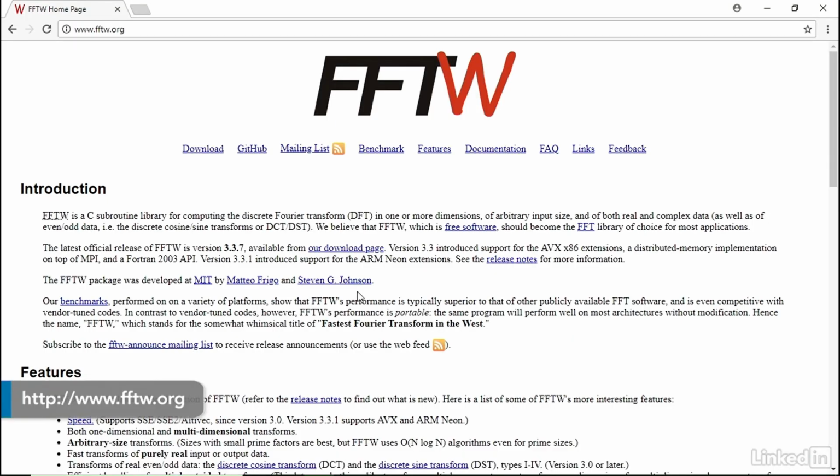Here, let's see how to use a dedicated FFT C library named FFTW to do a simple signal processing job. This library can work on many systems, although there might be some adjustments required. In this demo, we'll generate a sample time series signal and calculate the frequencies contained in the signal with FFT. In reality, this signal may come from monitoring sensors on a machine, and we can check if the frequencies out of these sensing signals are normal or not.